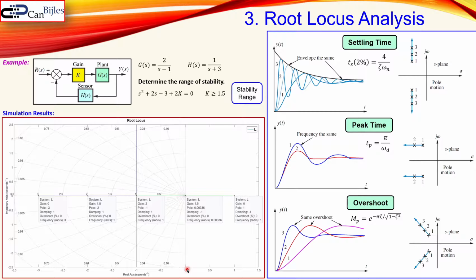You see here, that is the situation where you have the pole now at the border. Now when you increase your gain, for example to 2, you get actually here at the intersection. So this is again a proof that this is indeed correct. So the k must be indeed larger or equal to 1.5.